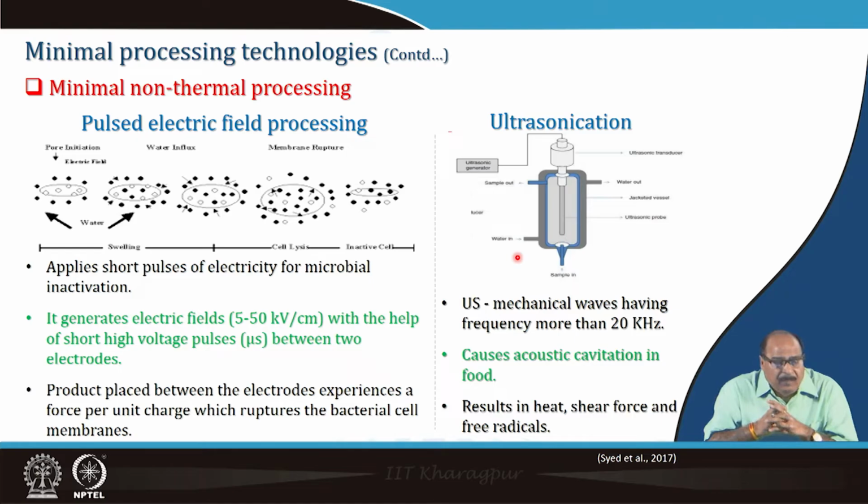Similarly, minimal non-thermal processing may also include pulsed electric field processing. It applies short pulses of electricity for microbial inactivation. It generates electrical fields with the help of short high voltage pulses between two electrodes, and the product placed between the electrodes experiences a force per unit charge which ruptures the bacterial cell membranes.